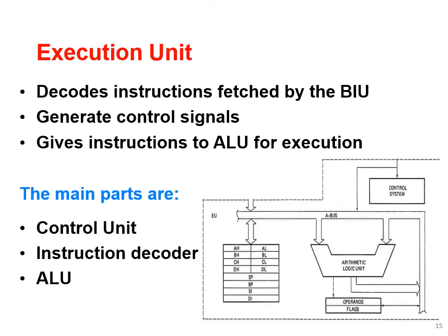And then you have seen the execution unit, which will decode the instructions fetched by the BIU. Very simple: the address summation block has calculated the effective address, and so the execution unit will be giving only the offset address of either the instruction or the data, whatever it requires. It only handles offset addresses because that's all it can do with its 16-bit capacity registers or data bus.